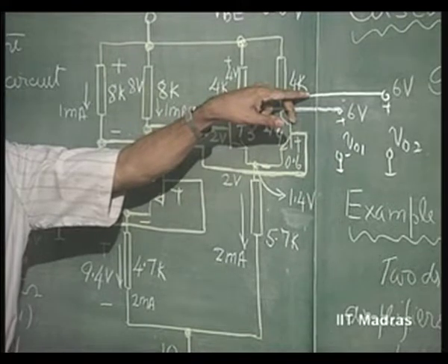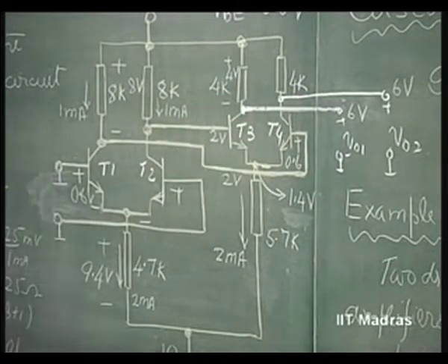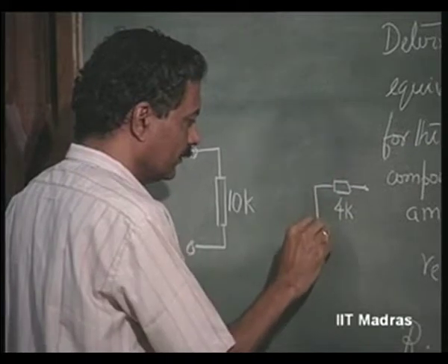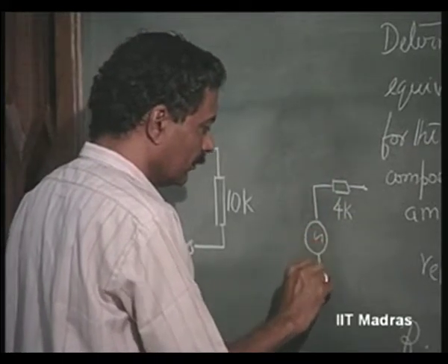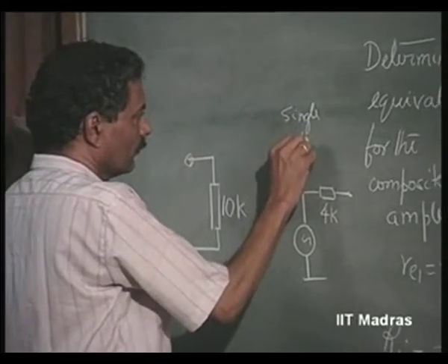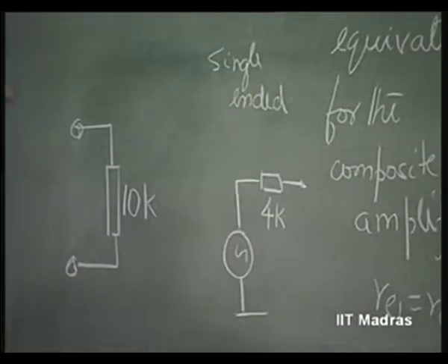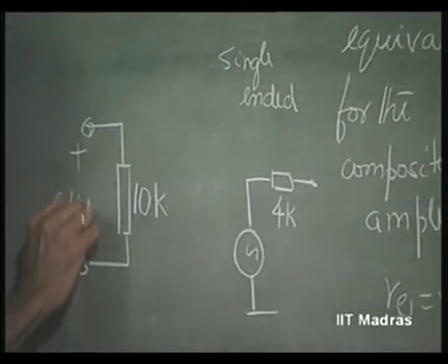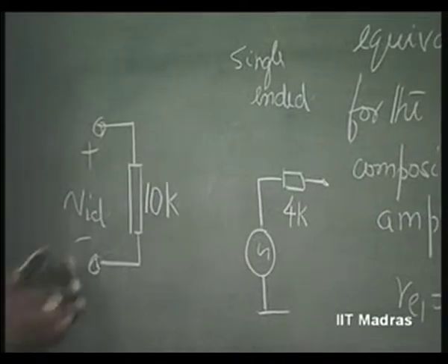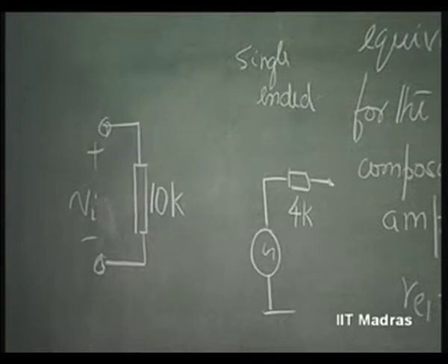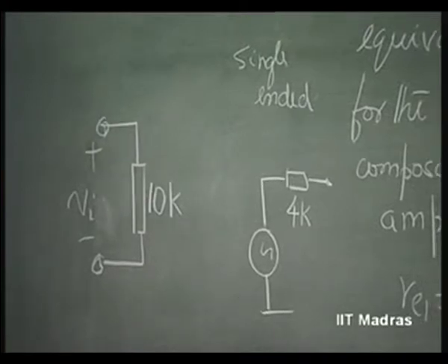Right. So, let us consider the single ended output. For that, output impedance is going to be 4K. This is single ended output. So, if I apply a differential signal, again this suffix D is going to be dropped in future, because for differential amplifier we are most interested only in differential gains.